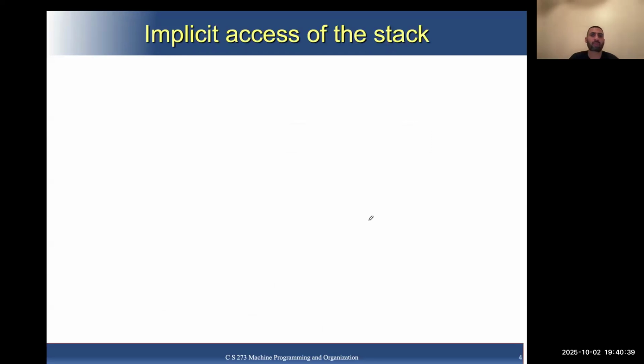Okay. So how do we access the stack? Whenever we want to put some data element on the stack, that operation is known as pushing the data on the stack. And for that, we have the push instruction in the AVR microcontroller. So you only need to execute push and then specify a register, right? As a part of execution of this instruction, the microcontroller actually puts the value of that register on the top of the stack.